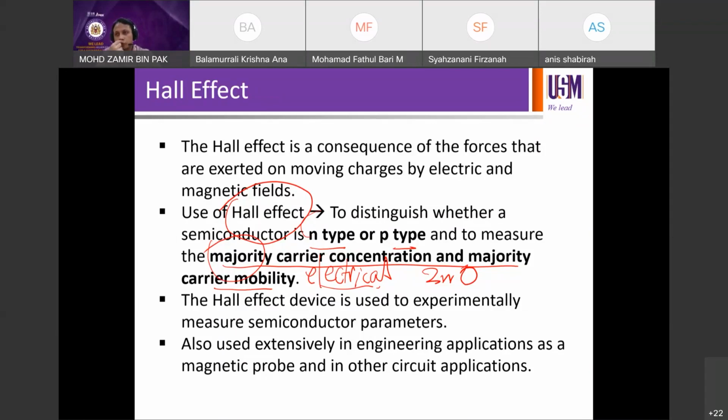You can also do a structural characterization, perhaps by Raman or XRD, X-ray diffraction. You can also use optical properties characterization, for example, by UV-Vis spectrometer. You can also do electrical properties, for example, by Hall effect, by 4-point probe, by IV characterizations.